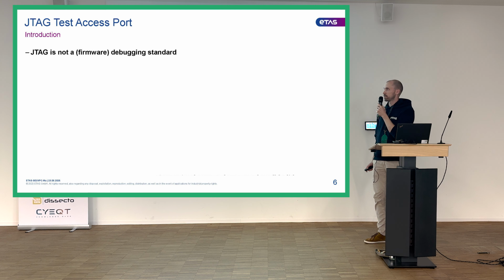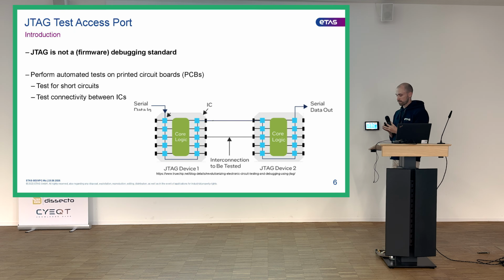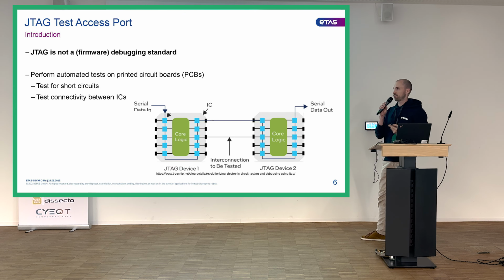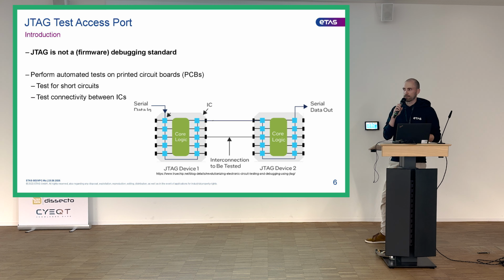First, what is JTAG not? JTAG is not a firmware debugging standard, which might come as a surprise. The original intention behind it is to perform automated tests on printed circuit boards. So your PCB comes out of the oven, and before you ship it to the customer, you want to check, are there any short circuits, or are all the interconnections functioning correctly? And this is what you might use JTAG for.